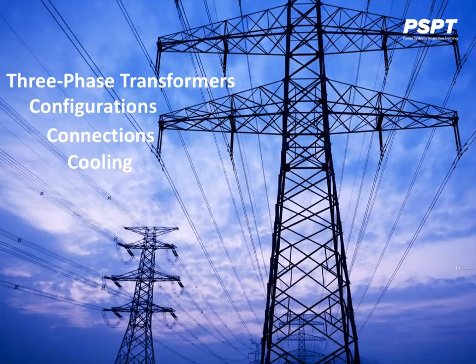In single-phase motors, the power transferred to the motor is a function of the instantaneous current, which is constantly varying. Hence, single-phase motors are more prone to vibrations. In three-phase motors, however, the power transferred is much more uniform throughout the cycle, and hence vibrations are greatly reduced. Mainly for these reasons, it is found that generation, transmission, and distribution of electric power is more economical in a three-phase system than in a single-phase system.